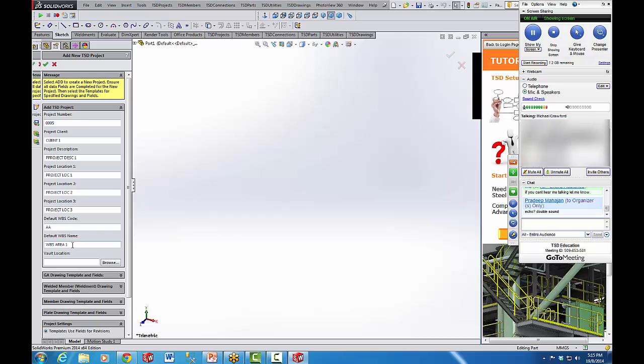However, you can call it whatever you like. You can go A, B, A, C, A, D, A, Z right through and call whatever the information that's in there, whatever you like. This is the WBS system. This is an area. WBS stands for Work Breakdown Structure. Okay, big mining projects have a WBS system. Okay, the reason I say that is because I come from a mining background, and I've used big mining projects down to the smallest little awning, and I've created areas for little things like that.